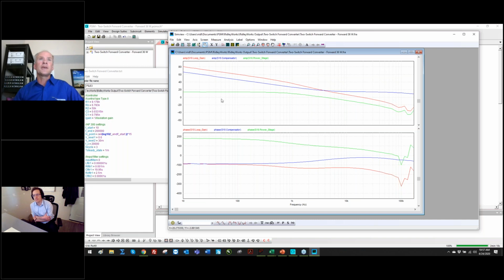Why is that? Because you got line noise. You got 50 hertz, 60 hertz, 100 hertz, 120 hertz. If you don't know your line rejection at 50 hertz, you can't be in the audio amplifier business. Otherwise, you're going to get hum coming through the output. So loops, the old HP machines, they always started down at 10 hertz. We've just done that in Psim.